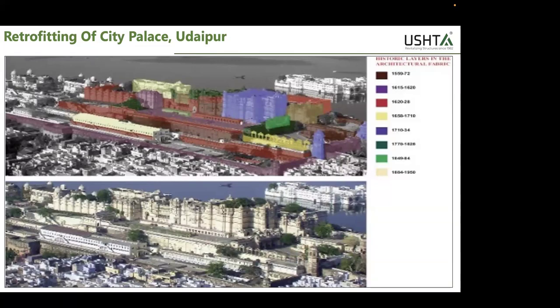So what happened was, it was designed for a ground floor, and suddenly 6-7 floors were added on the top. So the ground floor started cracking. Once it started cracking, the common thing was they added walls to make that load transfer happen.